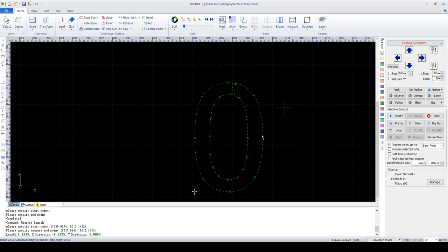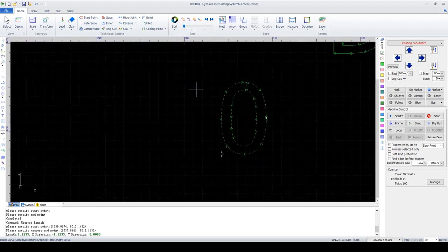Now let's come to the last feature. If we don't want parts to get automatically optimized when input, click Manually Optimize. In the drop-down menu, we have this break grid, which is used to cut up the inner waste so as to avoid it going up and getting in the way of the cutting head.